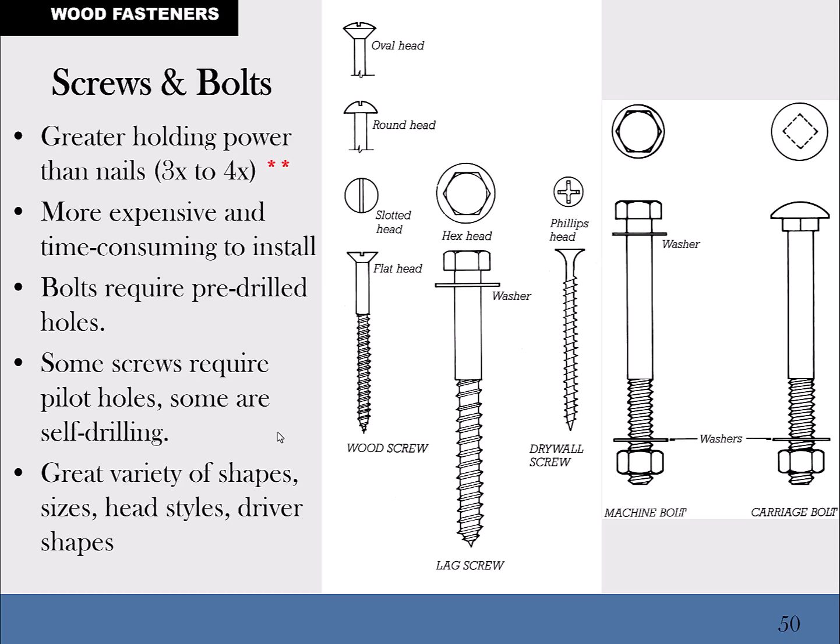It's good for at least that amount. Whereas a number 9 3.5 inch decking screw, similar sizing, takes up to 400 pounds to pull out, just grabbing a hold of the head and prying it out with a crowbar. So the screw has much more holding power.